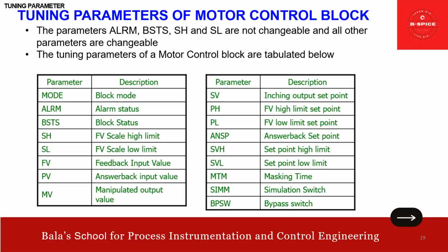Actually, there are many functionalities, friends. Of course, I'm not going to cover everything in half an hour. But for example, you can see here inching. What is inching actually? Inching is a function which drives or stops the motor for a specified duration according to the manual operation of the operator using the operation and monitoring function. That is the inching function, inching output.